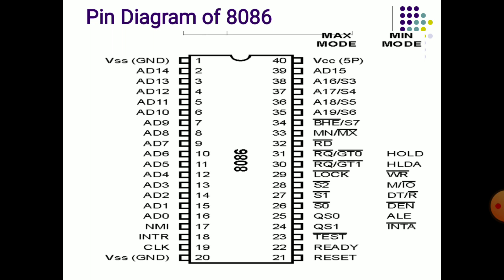It performs complex exponential and factorial type functions. Those complex functionalities can be carried out by that type of processor. So if our design needs some complex mathematical functions, we need to interface an extra, additional processor to the main CPU. That can be done using multiprocessor support. That's why this 8086 microprocessor supports both single processor mode and multiprocessor mode.